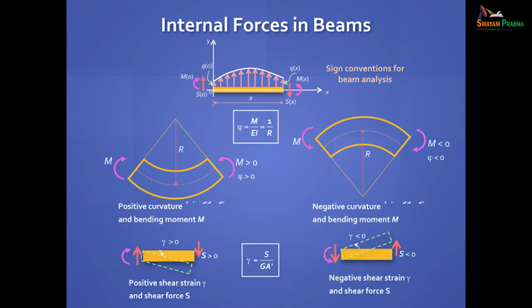All right. And there is a relationship. Look at here. Always there is a force and there's a material property, which is the modulus of shear rigidity G, which is related to E, you know that in terms of Poisson's ratio. And you have a dash. We don't write A because there's a correction for the shape. Because the shear stress is non-uniformly distributed. So this you may not use much, but this is something that you always need to use.